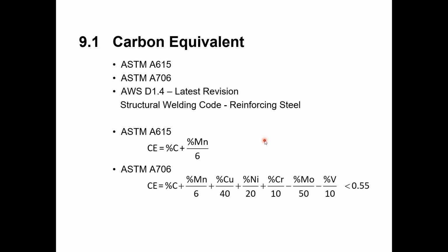And it says that the preheat temperature is none or 50, which most of the time it'll be that temperature anyway, unless you're in a really cold environment. There is a footnote, and those footnotes are below the table and continued on to the right-hand side of the page opening. It says, when the base metal is below 32 degrees Fahrenheit, the base metal shall be preheated to at least 70 degrees Fahrenheit or above and maintained at this minimum temperature during welding.